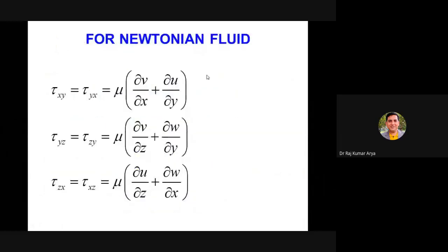Now, after that, let's say we are considering Newtonian fluids. Newtonian fluid, I have given in your chapter 1, where we talked about fundamentals of fluid properties, where I told you that tau yx is given by mu del u upon del y, right? Now here, because you have 2D planes, you will have x component of velocity and y component of velocity also. You have both the components of the velocity.